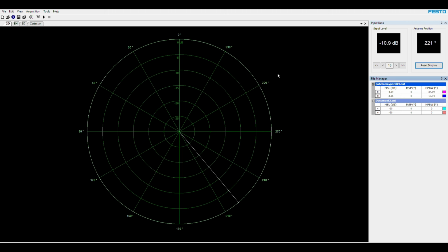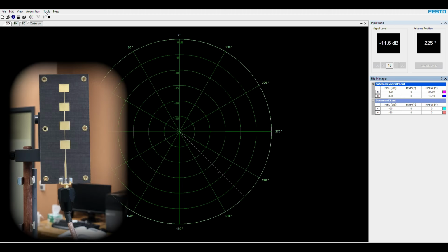Okay, the RF signal is now on. I have polarization of the horn antenna vertically polarized. Polarization of the antenna under test is also vertically polarized, and I'm rotating it in its H plane. So let's start our measurement and see what we're gonna get. And I kept the same distance as in the previous case, as instructed by the lab vault student manual.